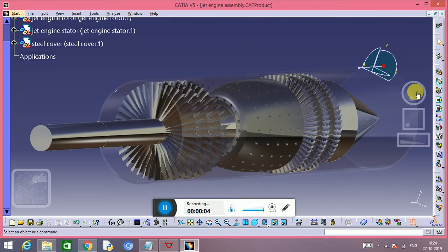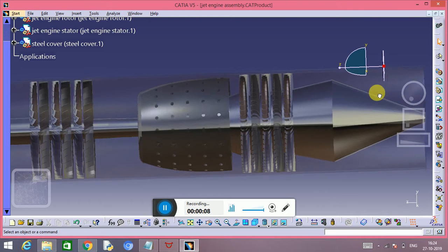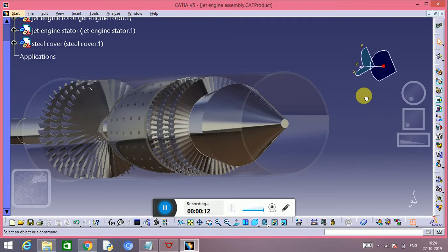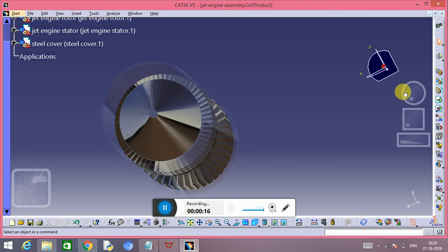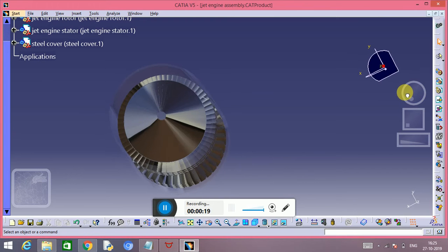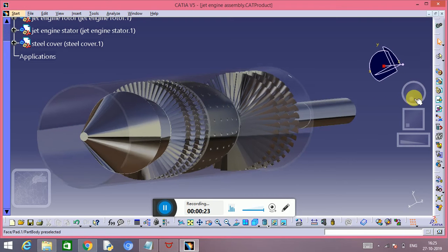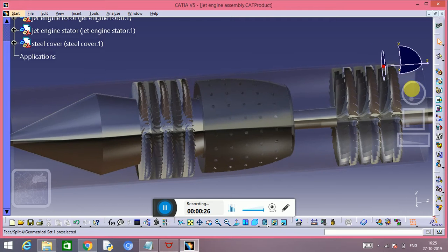It takes air from outside, compresses it with its axial compressor turbines, and then does combustion to further increase the pressure of the air to a very high value, and then ejects it through a nozzle having a small opening. In this way, pressure energy converts into kinetic energy of the jet, which gives the plane forward thrust.